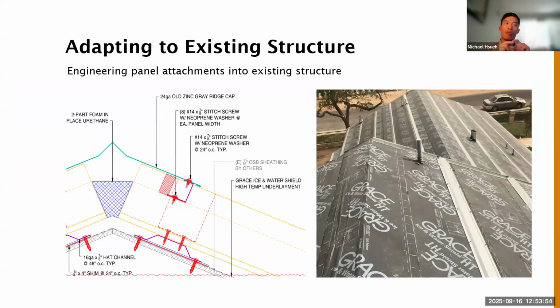The reticulated foam is an air baffle that mitigates wind washing underneath those panels to a significant amount, but still allows water at this plane to drain out at the roof edge. We're assuming not very much water is going to get underneath the panel, but you always assume that it will, and for it to drain out, there is reticulated foam in that gap.